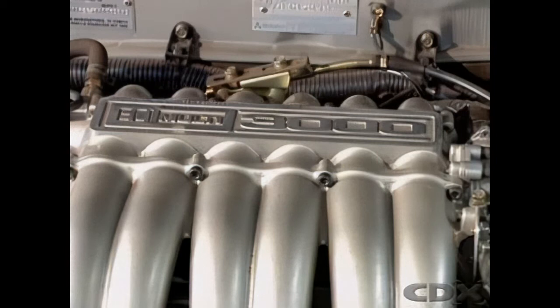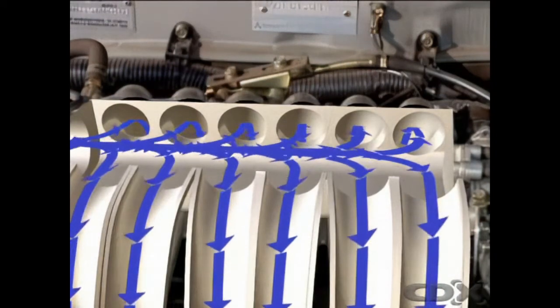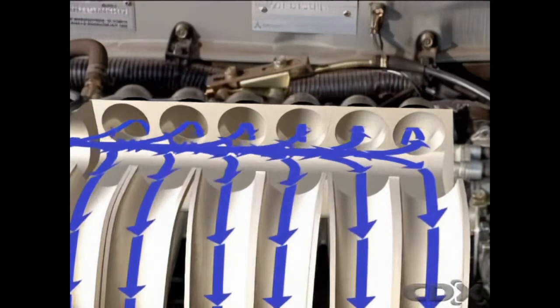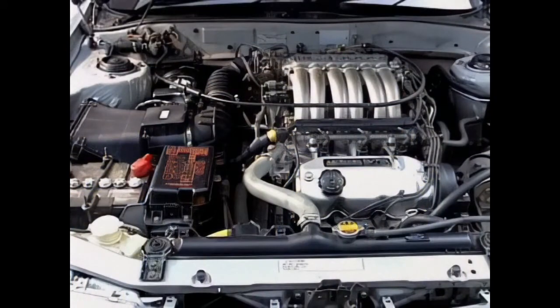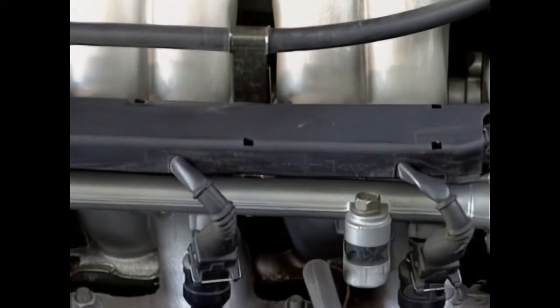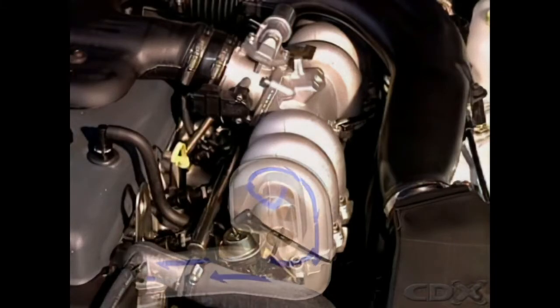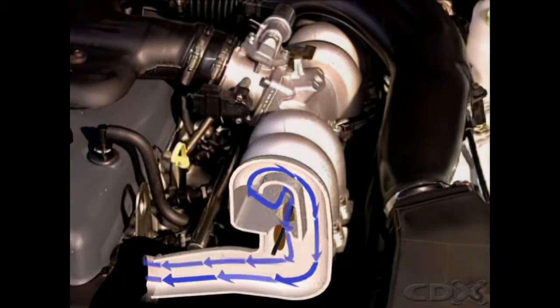This fuel-injected engine manifold has a plenum chamber that provides a reservoir of air and helps prevent interference with the flow of air between individual branches. It also acts as a silencer. On this primary manifold, the intake pipes are fixed in length. Other kinds of manifolds have extra valves to change the effective pipe length. They may be computer-controlled by the engine management system to open at a specified engine speed and extend the torque output.